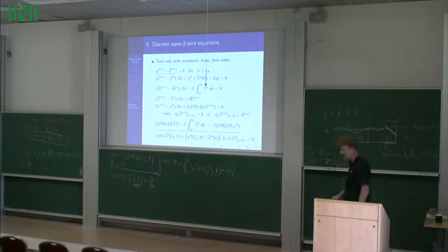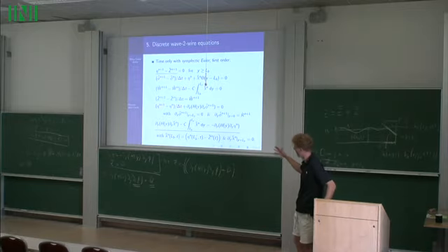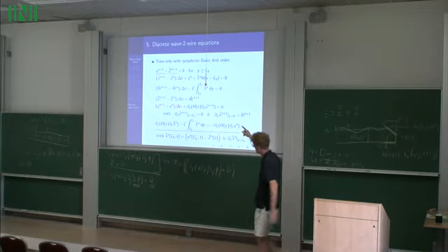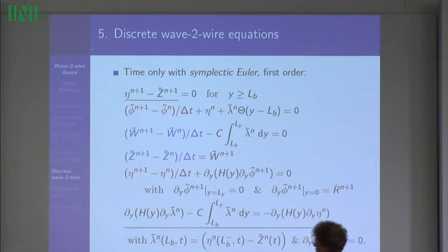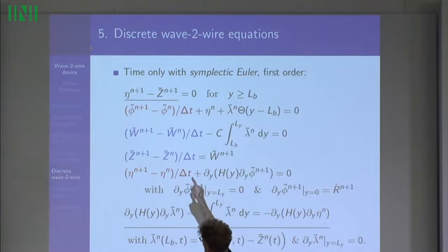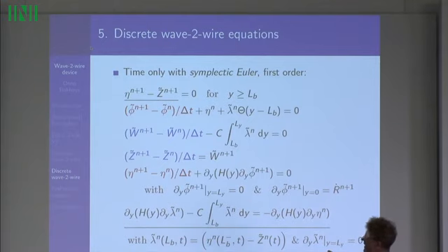But Ralph thought it may be due to the fact that you couple, and he was suggesting to remove zeta from being an unknown and impose it as a given function. So rather than having this buoy moving freely, you force the motion, and that means that zeta of t is a given function, just to check whether it being an unknown causes the problem.